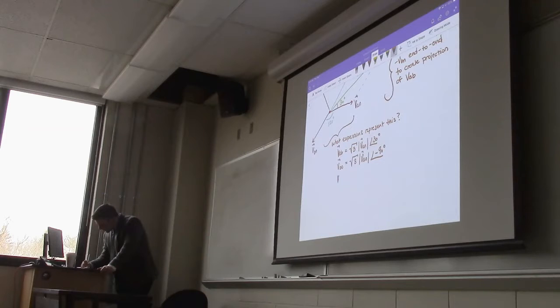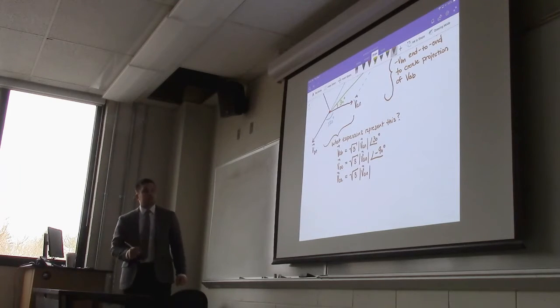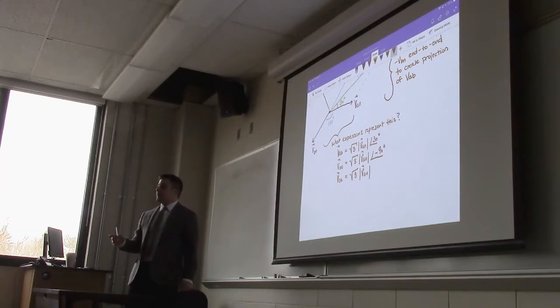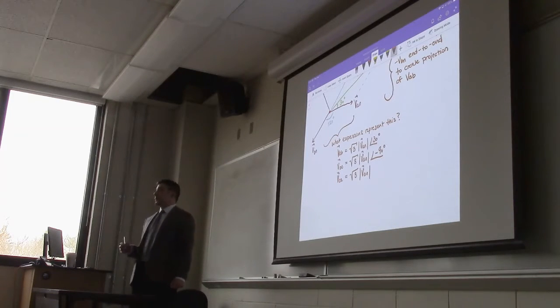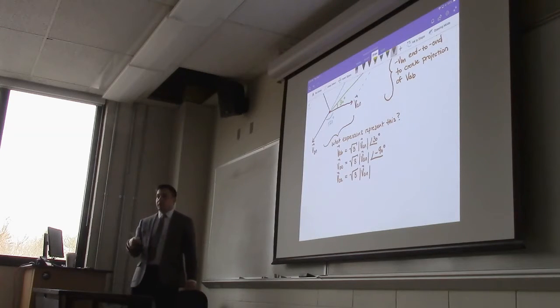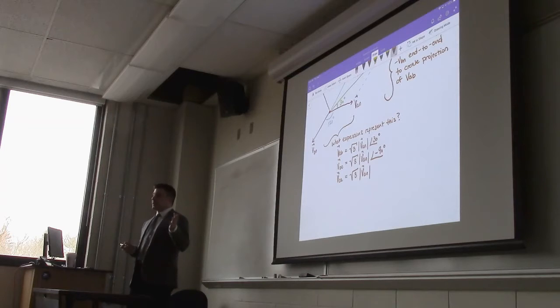And then VCA is equal to square root of 3 VAN. Remember that we're only taking the magnitude of VAN. If you wanted to, you could say magnitude of VAN, magnitude of VBN, magnitude of VCN, but they're balanced, so all the lengths are the same. So you could write them all in terms of the length of VBN, or all in terms of the length of VCN.